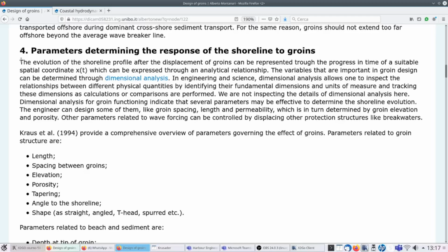So the sediment transport is stopped, and you have an accretion before reaching the barrier, because the sediment transport needs to go to zero. And then when you pass the barrier, you get a sudden increase of the sediment transport, and sudden increase means erosion.